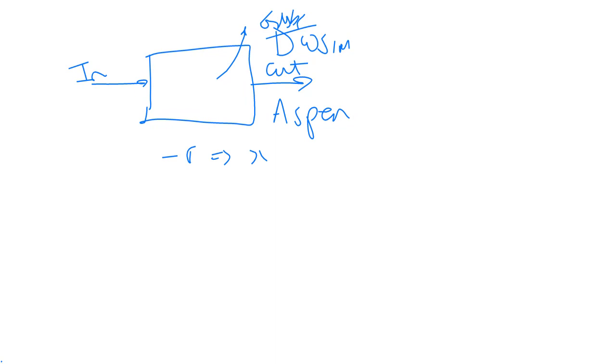And how does Aspen then do your energy balance? What it does is it considers the enthalpy of everything that comes in and the enthalpy of everything that goes out. And it's not going to use this Dow enthalpy approach that we are using, because it's got a database of lots of values, like steam tables.